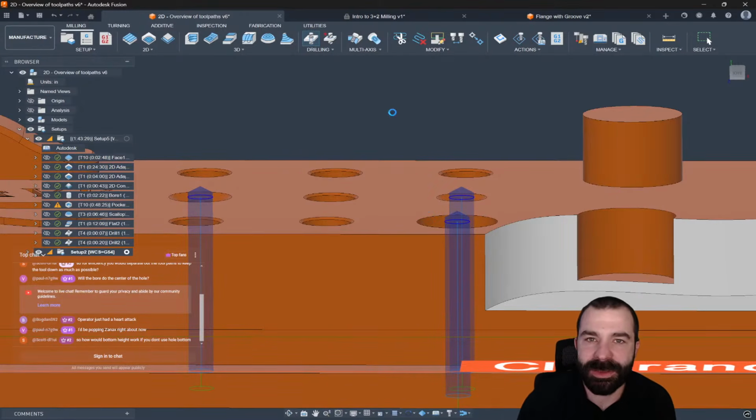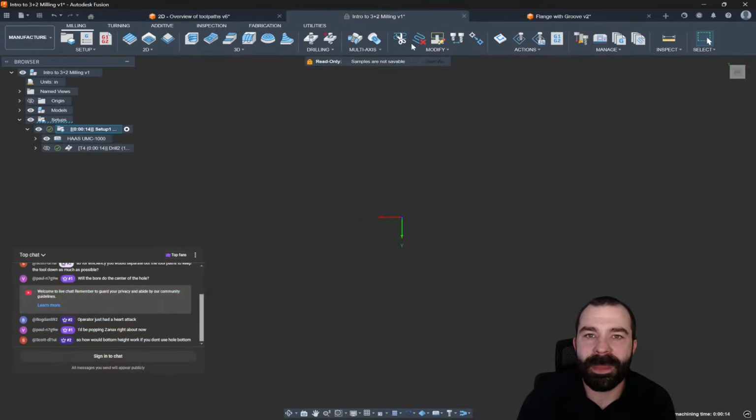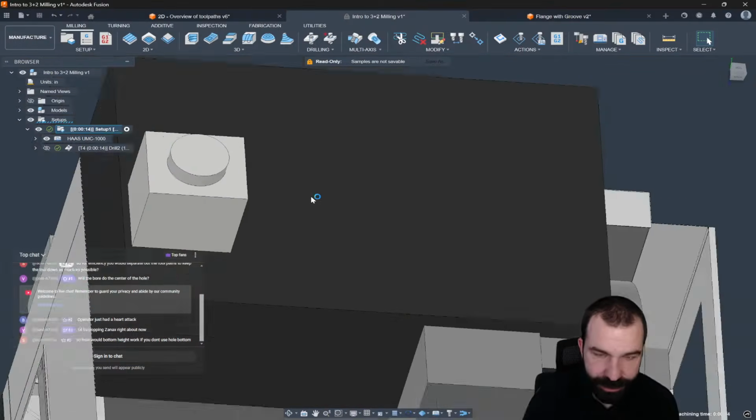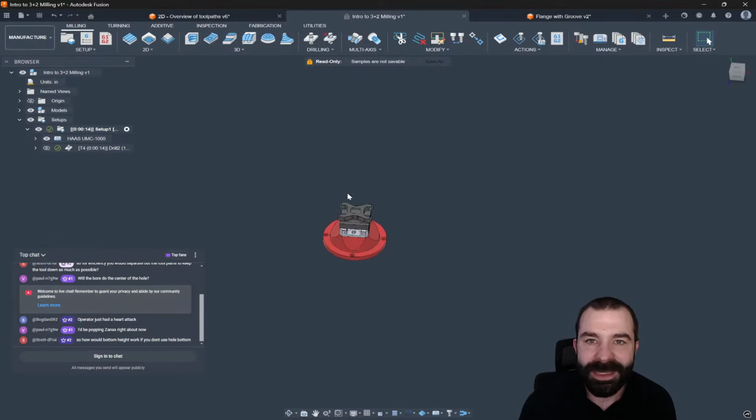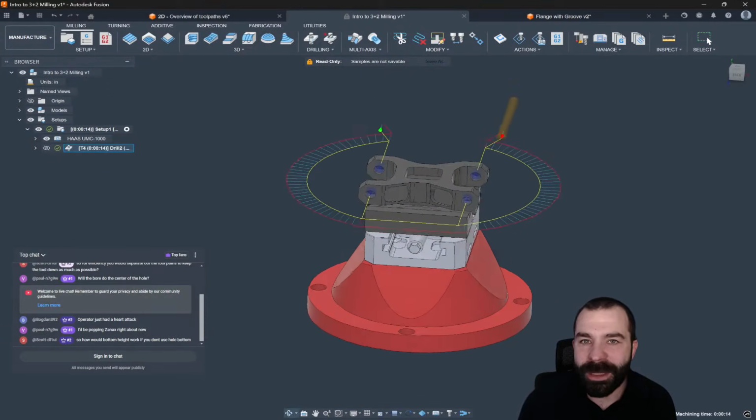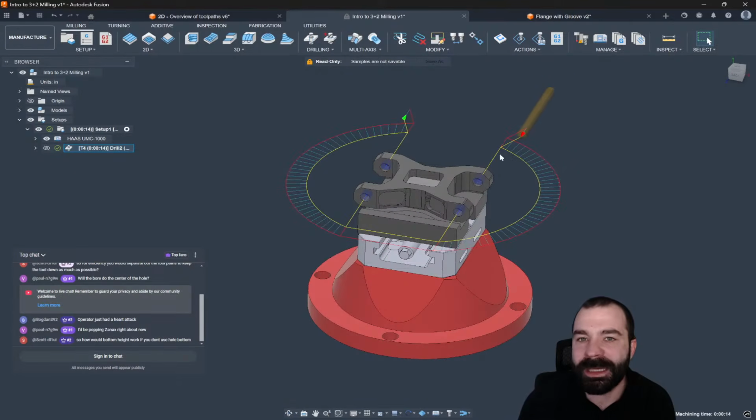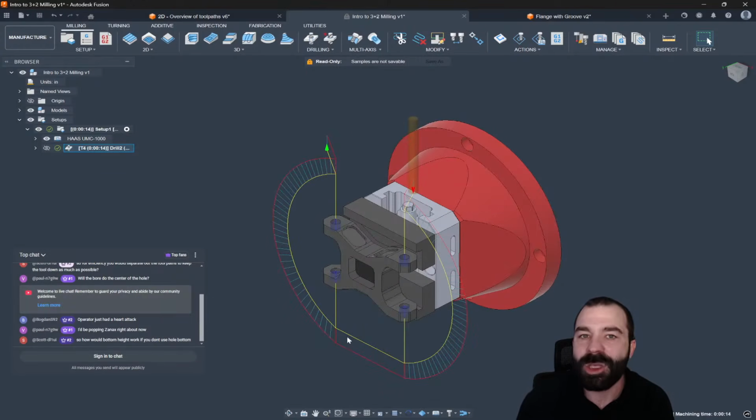We're going to go ahead and jump back to our 3+2 part. So again, that 3+2 part, as we went through, let's go ahead and do the old F6 move to figure out where our part is again, when we adjusted our heights tab so that we can get away from our part quite a bit. Now, on a 5-axis, it's a little more forgiving because we are very much fixture and model aware. On a 4th axis is where you would get in trouble if you think about swinging a tombstone around, right? You may have parts on all sides of that tombstone, so you have to make sure your tool gets up high enough and clears the tombstone.